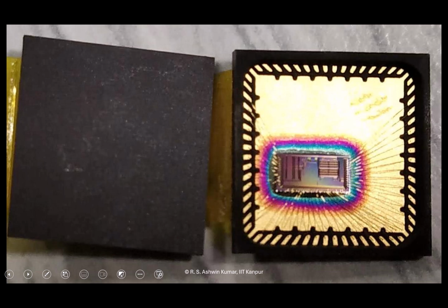So this is a chip that I taped out some time back, and this is the actual silicon die, and you can actually see the gold wires connecting here. Here, if you see, I have placed the silicon die closer to the left side. So what can you say about the inductance value on these sides? Smaller. That's exactly the reason I try to place these pins closer to the left side. But what is the downside in keeping it to the left side? Yeah, the other side will have a longer inductance, right? So that's the trade-off.